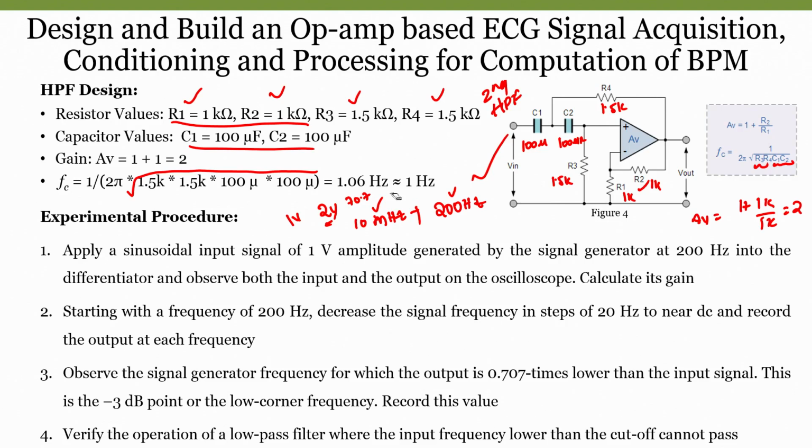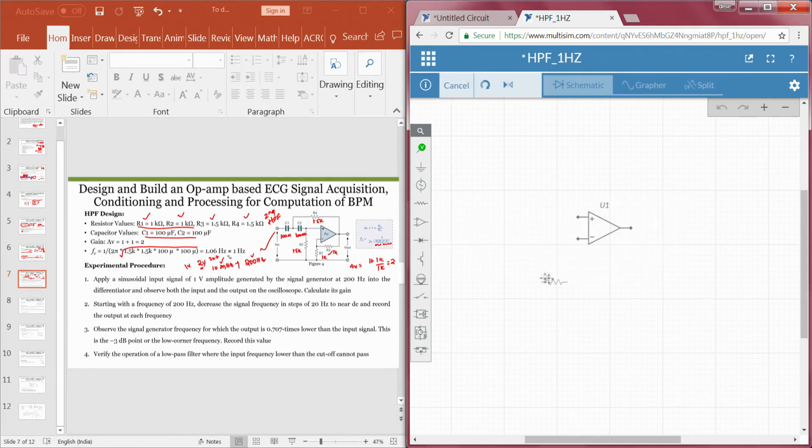So, I will use the same resistance values as well as the same R1 notations too. So, R1 I am keeping it here and rotating it, and I am also taking R2, this is R2. R1 and R2 are the same resistance value. So, I do not have to change the resistance, I will be connecting it here, negative feedback, right. So, the input resistance and the feedback resistance, which decide the gain of an op amp, are done.